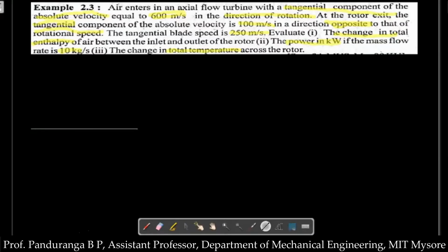So here I'll draw a regular velocity triangle. It's the normal velocity triangle which we used in the previous class. I'll be writing this for all the problems, just for reference. Whenever we are solving turbomachine problems analytically, we need to have this velocity triangle for reference to find the different velocity components.